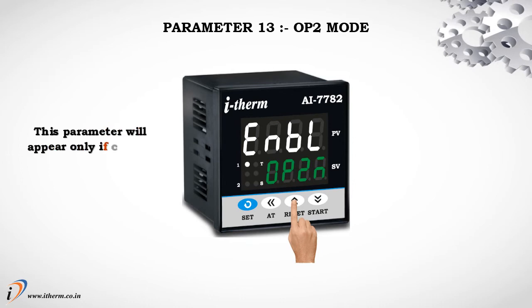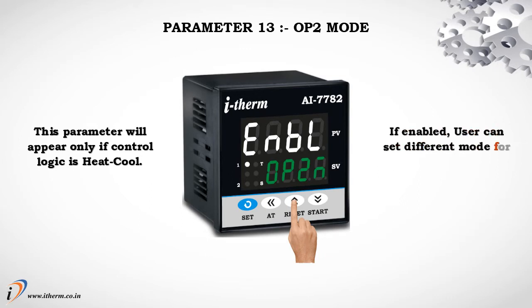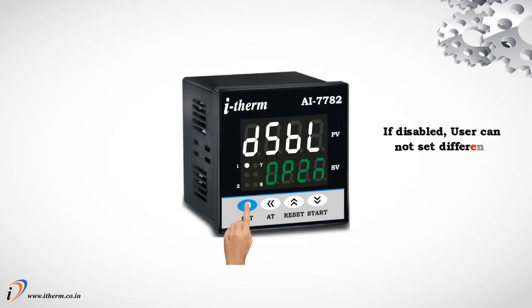Parameter 13, Output 2 mode. This parameter will appear only if control logic is heat-cool. If enabled, the user can set a different mode for output 2 in the user list. If disabled, the user cannot set a different mode for output 2 in the user list.